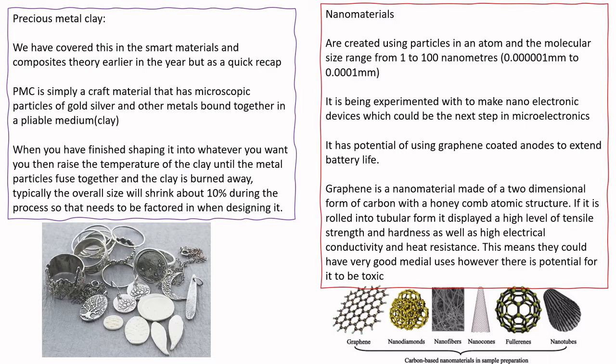Typically, because you're removing the medium, the clay on it, it ends up shrinking by about 10%. So when you're designing and making it, you need to factor that in because it does shrink.